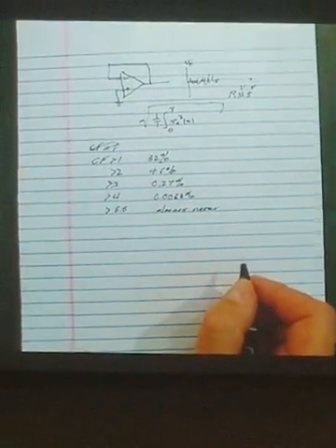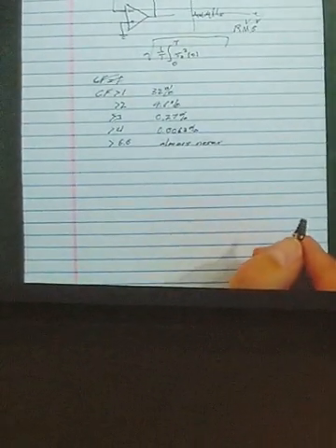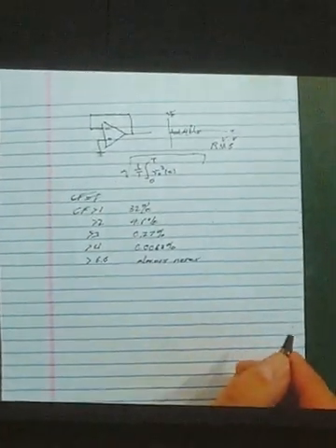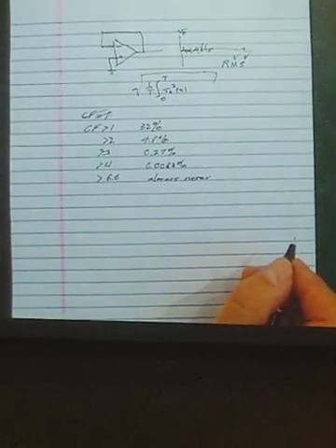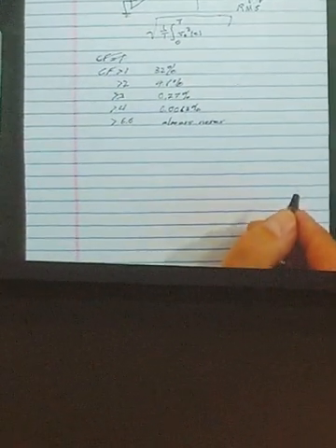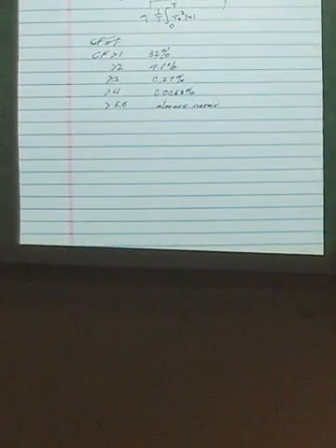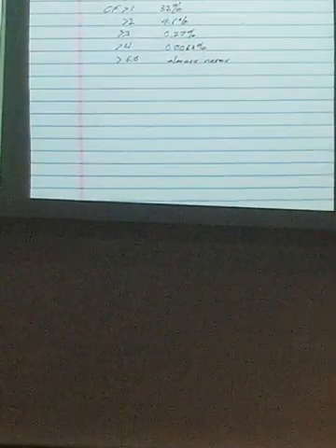So when you gain that signal up, let's say by a factor of 1,000, 60 dB, well, then that would be plus or minus 6 volts, which certainly exceeds the input range of any reasonable A to D. So you want less gain than that.